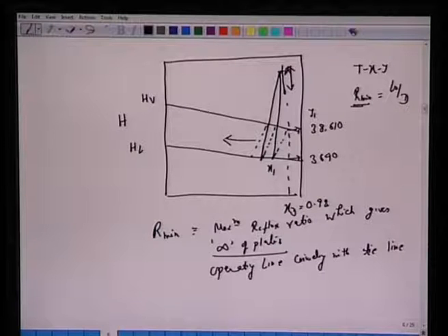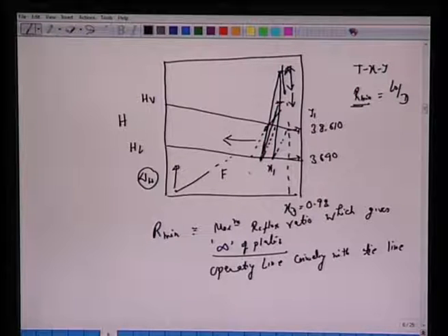All right, so look at the slope of this operating line and the slope of this. As we go down, the slope of this line will change. So if del D is here and we connect with a certain point here, you can see that this line is gradually becoming parallel to this, and since this WD goes down and we have F which is fixed, XW will also change, will also move upward. All we have to do is find that tie line which coincides with this operating curve.